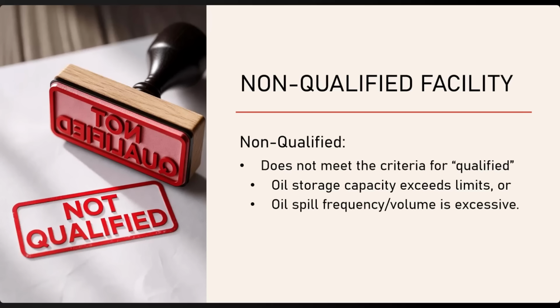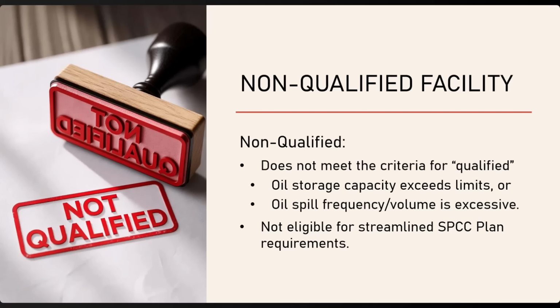There are a couple of important definitions that are essential to this course. The first is a non-qualified facility. Actually, this is sort of a default way of expressing the fact that the regulated facility does not meet the definition of qualified facility. In other words, the amount of oil stored exceeds the amount allowed for a qualified facility, or the frequency and volume of oil spills reaching navigable waters or their shorelines exceeds what is permissible for a qualified facility. Because the facility is non-qualified, it is not eligible for the streamlined SPCC requirements allowed for qualified facilities.